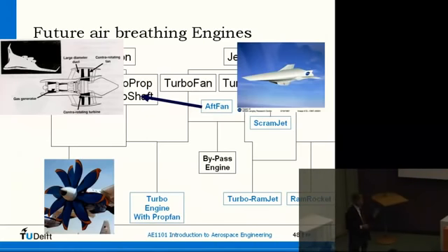Of course, there's also recently we saw military hypersonic vehicles. There's still research ongoing for hypersonic vehicles, and they use ramjets, but then a different type of ramjet. In all the aircraft that we have seen so far, the air is compressed but also reduced in speed. In all engines that we've seen so far, the speed inside the engine is subsonic, because otherwise we get shock waves and all kinds of trouble. Similarly for a ramjet, the air is compressed and reduced in speed, but with a scramjet, we want to keep the flow supersonic in the engine, and scramjet stands for supersonic combustion ramjet. So for high speeds, you can use the scramjet, but clearly not for lower speeds. So the trick is often how to combine getting to the high speed and actually flying at the high speed.